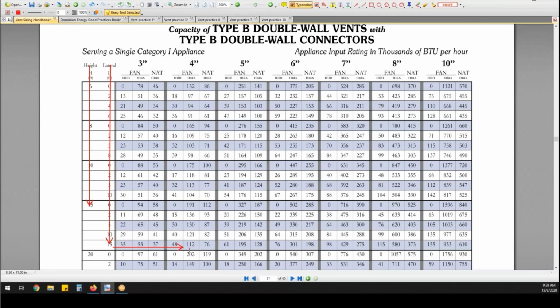And what happens to hot, moist air when it cools down? What does it turn into? Condensation. And do we want condensation inside of our metal flues? Absolutely not. So on fan-assisted appliances, it is critical that you fall within the min-max. We've got to keep it hot enough. If we don't keep it hot enough, it won't work. Everything will start condensing in there, okay?